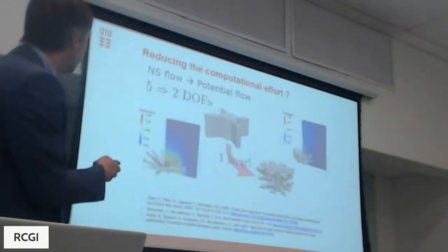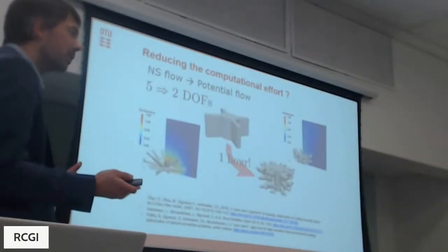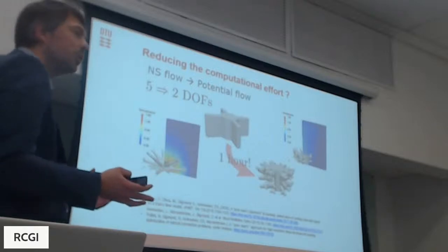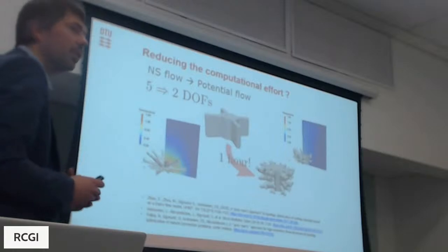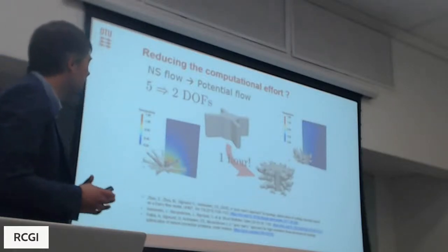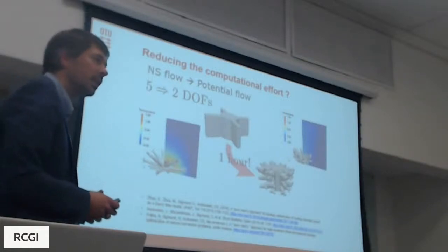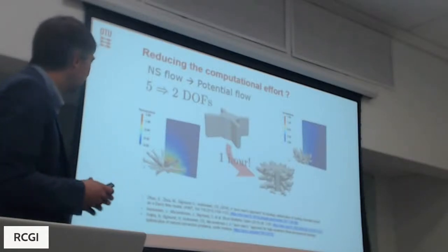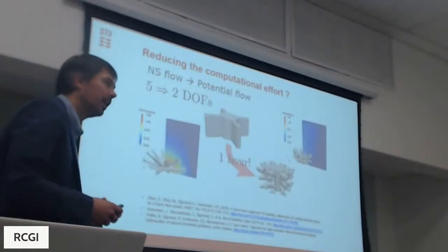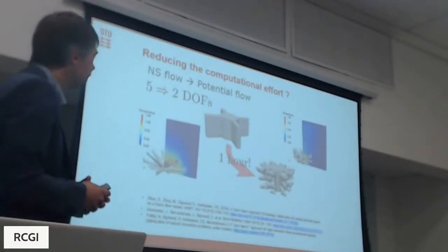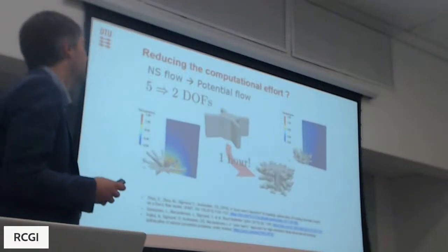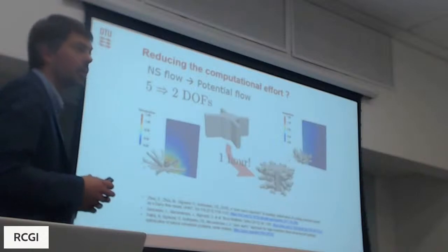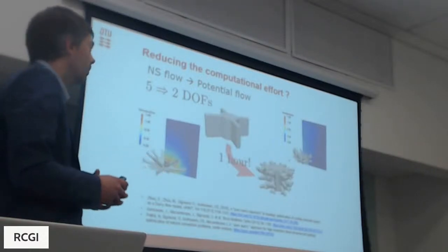Yes. Then the final slide, because all of this, solving all these Navier-Stokes equations for two domains and also the heat exchange is quite an expensive process and requires large computers. So we have also done some efforts in order to try to lower the computational burden, because for many problems here it's showcased in a natural convection problem. Then a lot of it is just trying to mimic how the fluid is actually moving. And that can, to some extent, be done by using a potential flow solution instead of solving the full Navier-Stokes equation.